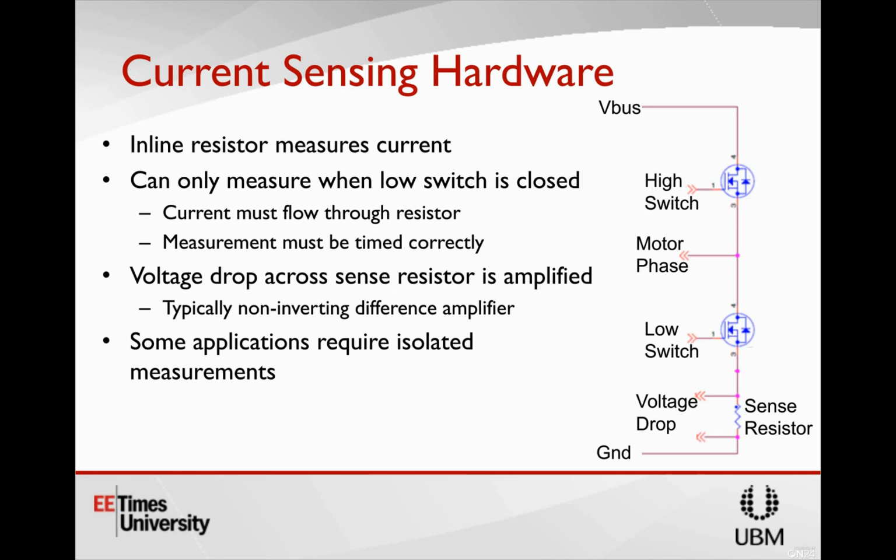And so obviously it's important when you design your hardware to make sure that you're covering the entire range that your motor is going to see in terms of current with respect to the range that's ratable by your MCU.